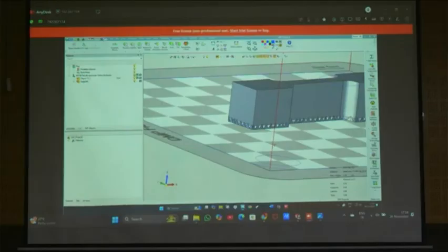At the base we have printed some solid wall actually. That is something tricky we found. We printed an extra solid wall. Or otherwise we can create a solid wall, like I told you with the tensile sample. Say I want to print a lattice in a 30 mm cube. I will add an extra 1 mm thickness of base so that I can separate the body. My design space is the 30 mm, and that 1 mm is the non-design space. I will apply the 30 mm lattice, combine the non-design space, and print it. So the 31 mm will come, and in that, I can cut the 1 mm. Right?